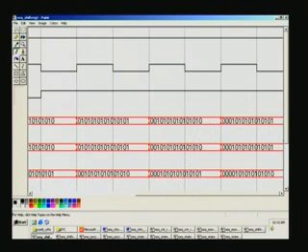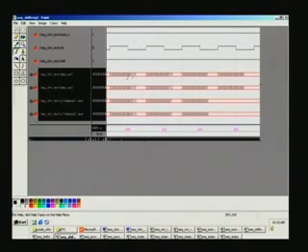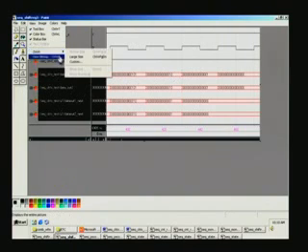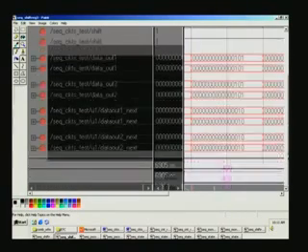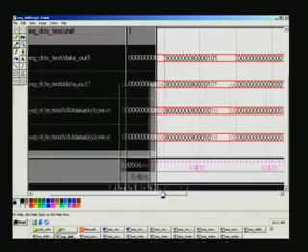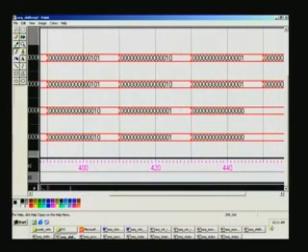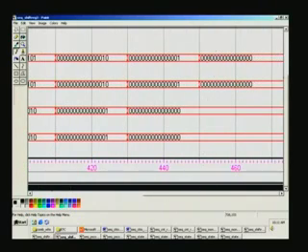And the last waveform gives the tail end of that. So once again we'll zoom in here. If you look here, the same pattern will be continuing. You can see 101 here, all zeros here, and all zeros here. This 1 will get dropped. So what you have is 10 here, and then this 1 will move here as shown, and finally that 1 also will disappear, right? So that's how you see a shift register working, right?